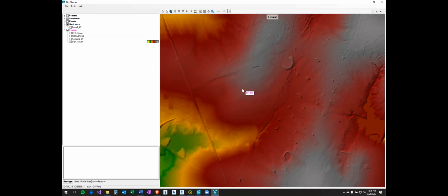One more question or clarification. Every time I prep anything for somebody in HEC-RAS, it needs to be in grid, so that everything is in grid instead of surface coordinates. Are y'all on the same page there? I am. I prefer everything to be the same, and since the majority of the data we use before the survey is on grid, I try to keep everything on grid so I don't have to deal with that conversion.